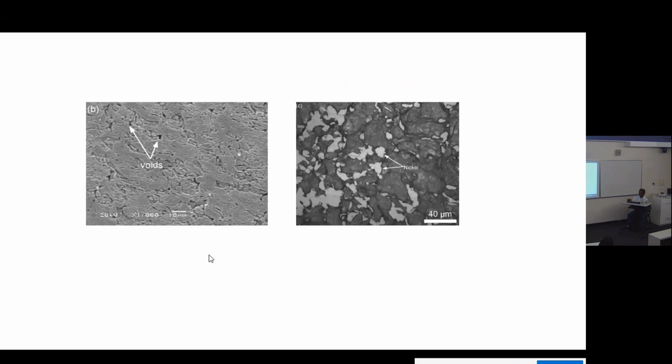So this is 20% nickel, and then copper were mixed together, blended together, and then it was sprayed. The normal way of making this kind of part or coating is to have an alloy powder, a powder that has already got 20% nickel and 80% copper.